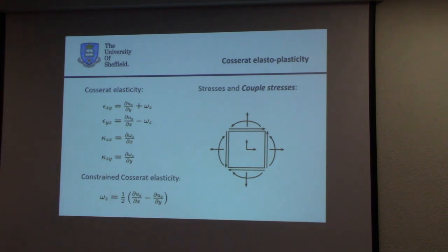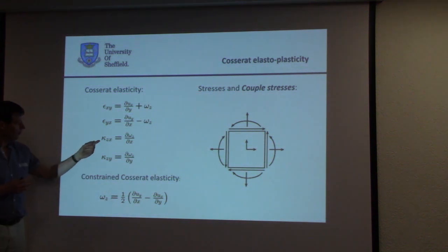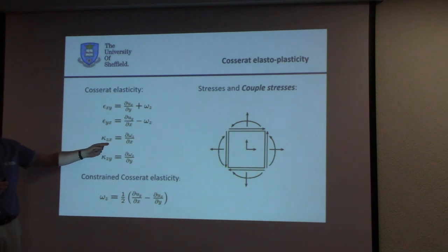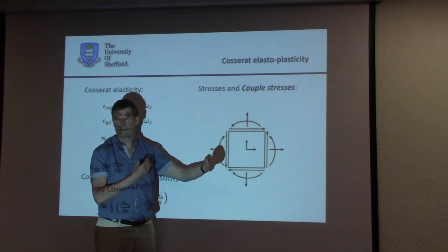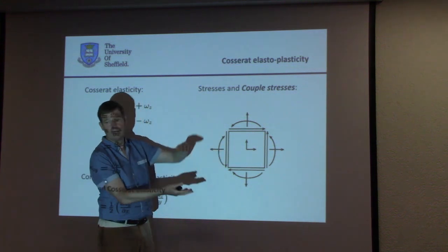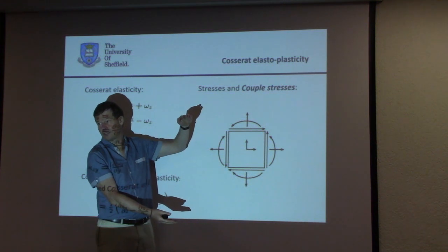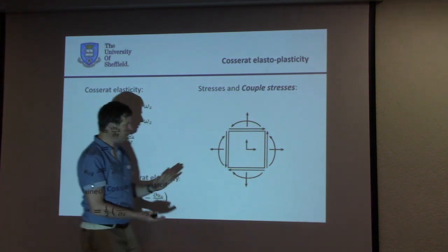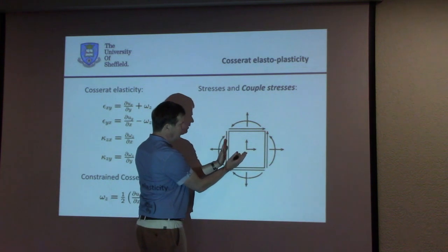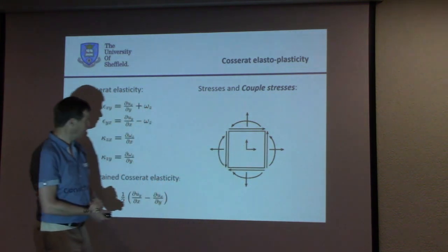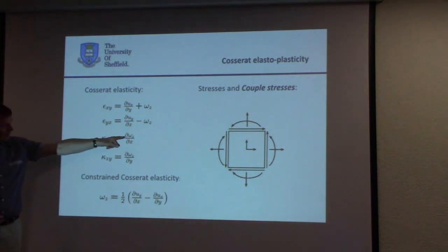Now, since we have a rotation, this kinematic degree of freedom, we also have curvatures, microcurvatures, which are possible. So for this elementary particle, we of course have the axial strain in x direction and in y direction. They are not affected, they are as before. We have our shear strains, a different one, epsilon_yx from epsilon_xy. But also, we now have our rotation, which can cause a curvature.